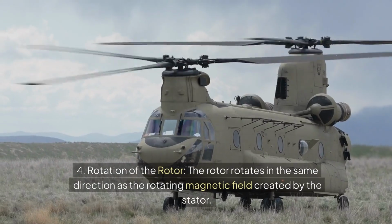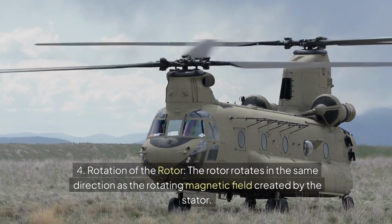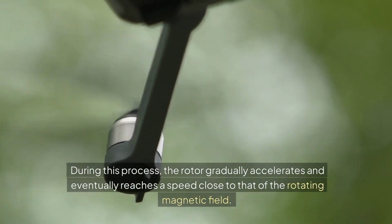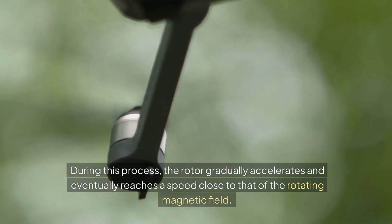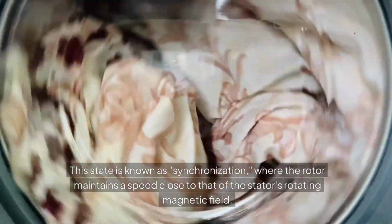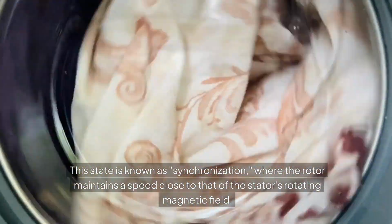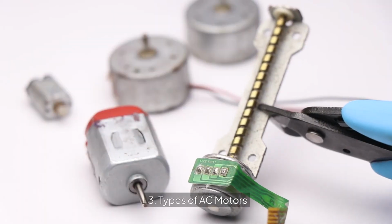4. Rotation of the rotor. The rotor rotates in the same direction as the rotating magnetic field created by the stator. During this process, the rotor gradually accelerates and eventually reaches a speed close to that of the rotating magnetic field. This state is known as synchronization, where the rotor maintains a speed close to that of the stator's rotating magnetic field.